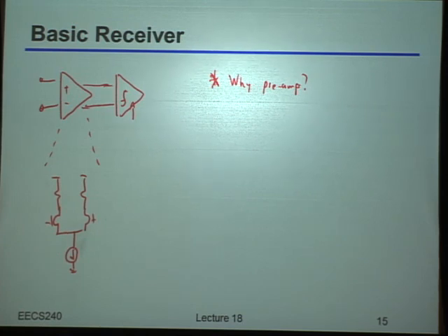So to fully answer that question, we need to know a lot more about how comparators are built. But for now, let me just state the following, and again, we'll see this very shortly. Turns out that those comparators, in order to really work the way we want them to, typically have quite a few devices in them. And in particular, have quite a few more devices than the preamp does. That really has two implications. The first is that they tend to have a lot more noise. Because if you have more active devices, all of those active devices contribute to noise. And the second, perhaps more important one, is that the fact that there's more devices also tends to indicate that there's larger offset.